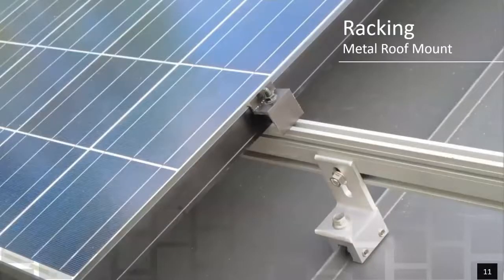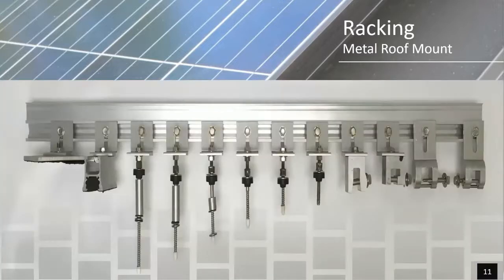The next one that we see, and it seems to be in pockets depending on your region, is metal roof mounting. Once you get off of the roof with your brackets, your L bracket or your S5 bracket like you see in this image, everything else is the same. Rails are the same, attachments are the same, your power optimizers or microinverter mounts are the same, everything's the same. The only difference is how you secure or fasten it. And with metal roofs, there are quite a few options depending on your metal roof.